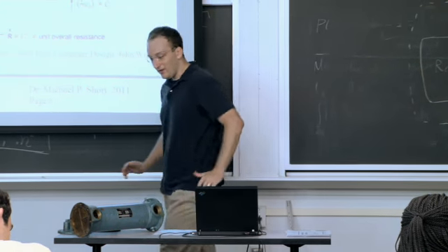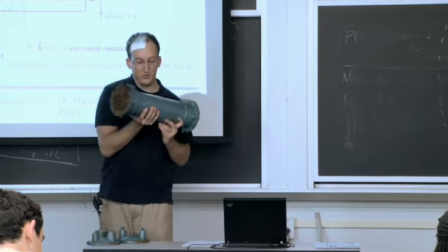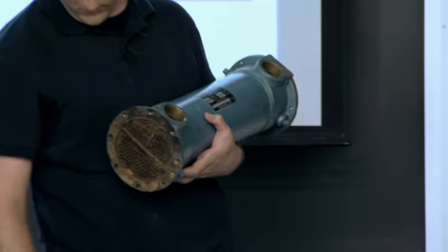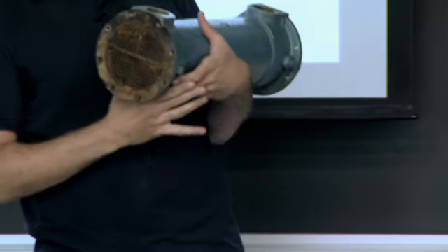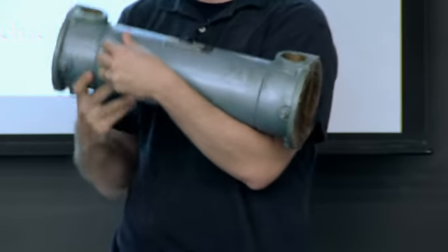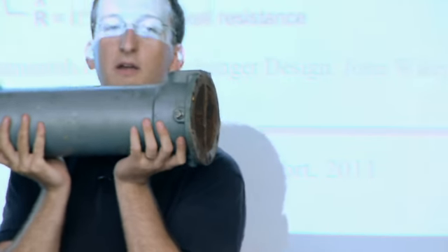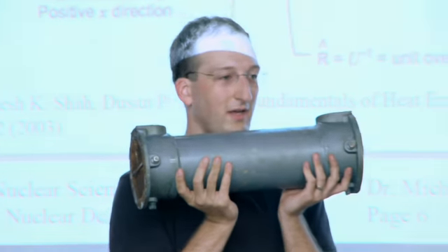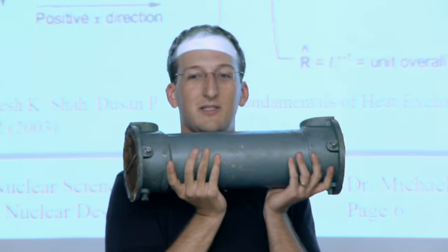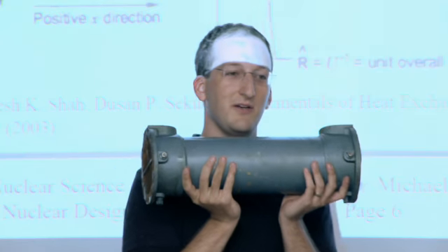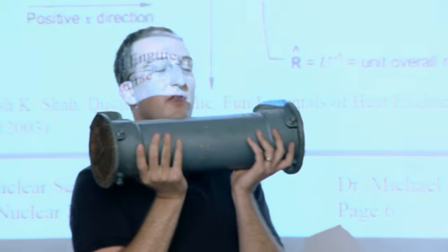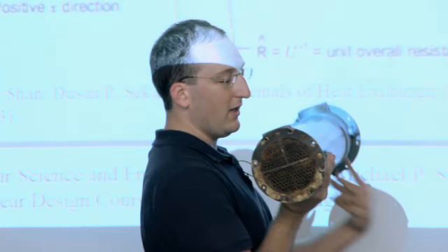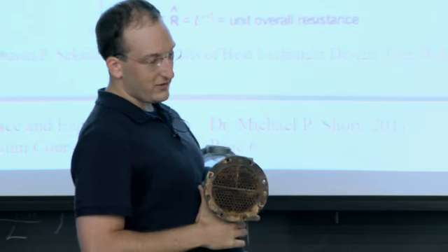They're everywhere. Here is a more serious heat exchanger. It's disgusting, so I won't pass around the end plates. But I just wanted to show you guys sort of what's possible. This thing right here can transfer 2,500 BTU per horsepower per hour. And since I know you guys don't know how many hogsheads are in a furlong or any of those other imperial units, this can put out about 30 kilowatts for a 40 horsepower motor, which is what we connect it to. It is a 4-pass heat exchanger.